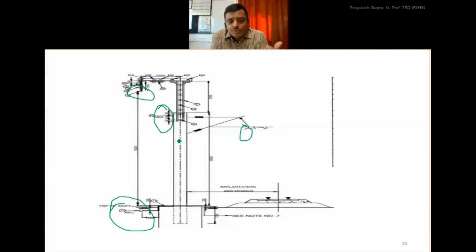So how we are going ahead if our existing mast fails. What we are going to do, we cast a foundation and a mast suitable for the local wind capacity, wind pressure. Second, suitable for contact, suitable for catenary, suitable for aerial earth conductor, suitable for feeder, all 5 things. So it will be a sturdy mast now.